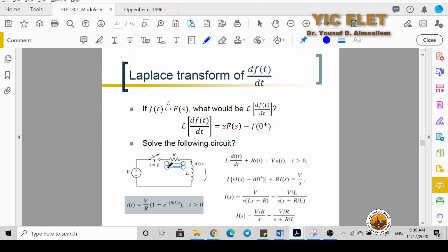If you're talking about resistance, you will replace it by a certain value, and if it is an inductor or capacitor, you will replace it by a certain value, and then you will do a simple calculation, and you will be able to find that the result moves from derivative equations, as you can see here, all the way to very simple equations like you can see over here. So this is much simpler to work with than the derivative equation, as you can see in this part.